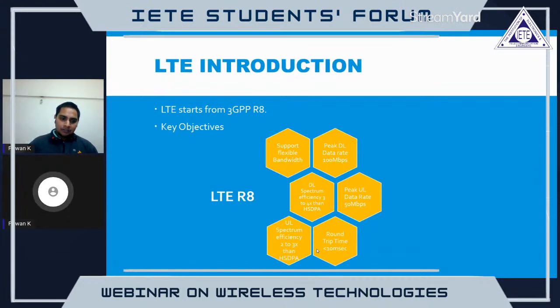Because we browse more, we download more, we get more information from the node compared to what we give to the node in the form of voice, data, or uploads, because our uploads happen in a much lesser time. So why would we use more resources for the uplink? For uplinks we will definitely use fewer resources, and for downlink we will definitely use more resources.